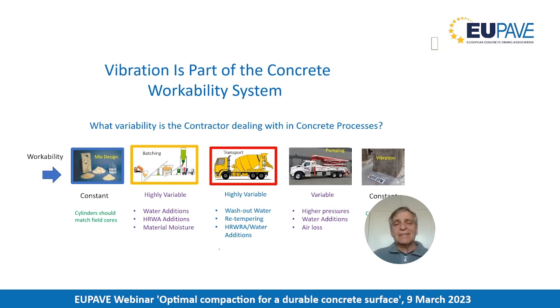In order to do that, we began to look at controlling vibrators and taking the actual energy that we apply to the workability system, or the mechanical resistance of the concrete, and focusing just on changes in that resistance, so we can match the two.